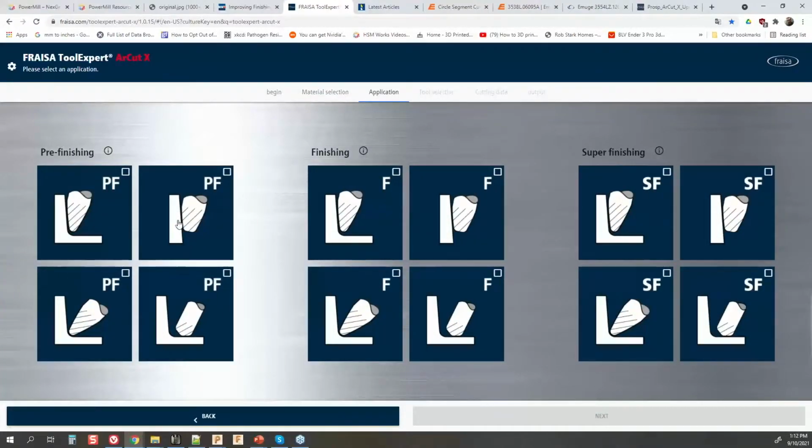Now, when we're looking at these types of barrel cutters, they do give us kind of a difference in what we're trying to do. Typically, I usually don't do a semi-finish operation with these types of tools. I'm focusing more on finish and super fine finish when we're trying to get down to mirror finishes on tools or something like that, or in aerospace when I'm trying to finish and get down on thin wall webbed type parts. You can kind of see, well, what type of tool and what kind of contact point are you looking for here for your tool?